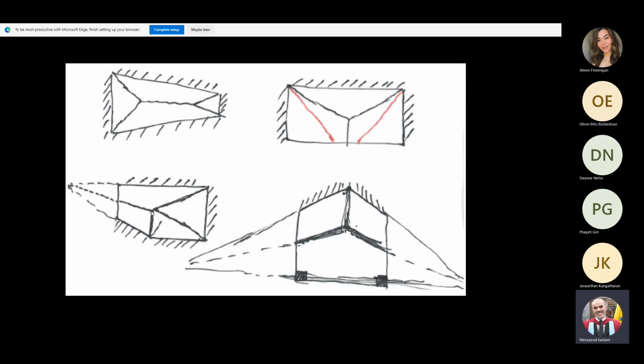Okay, it cannot go to this corner or this one, because this end is free. However, what you do, you extend this side and this side, which is simply supported. It gives you a point of intersection, and then you join from the point of maximum curvature to the point of intersection, and that gives you the yield line as shown here. Is that clear? Okay, so it gives us this yield line pattern.